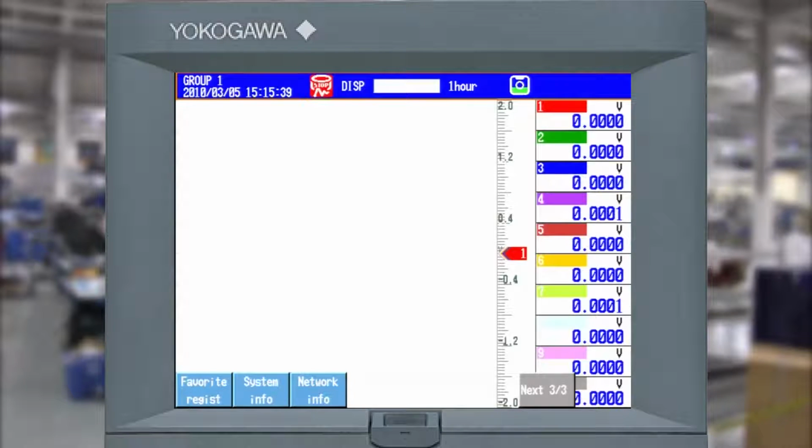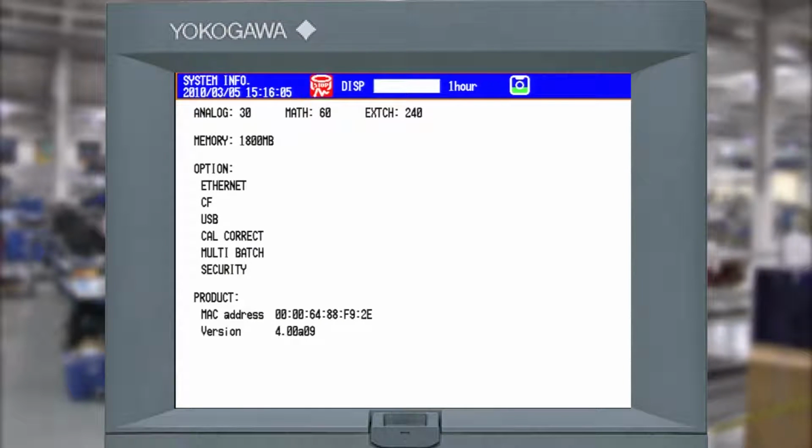And this system information is the one that's going to be of interest to us here. If you don't see system information, you've got maybe an older DAQStation, maybe it's just a regular DAQStation, not a DAQStation Advanced, then you might see some different choices under the function key. To get to system info, you'll hit the function key, then you'll pick log, and then you'll pick system info under the log. This one here can be accessed directly, so I'm going to hit that key right now. This tells me what I have right now for system info.